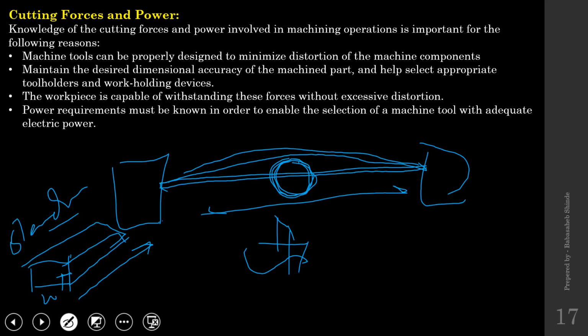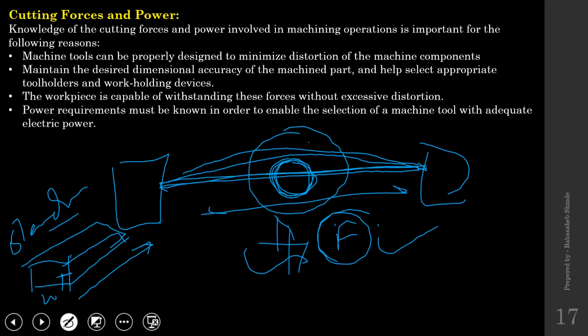So in machining of such workpieces, I need to have a better idea of the magnitude of forces to be generated, so that I will get to know whether this workpiece is capable of withstanding those forces. And once I have that idea, I'll continue with the machining. If not possible, I'll have to think of some alternative, right? So that is another thing that makes understanding the cutting forces necessary.